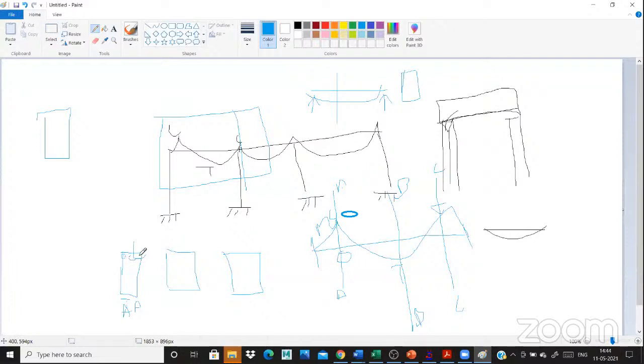So you provide the rebar in the compression zone. I provide 3 rebars for my compression zone. I provide 2 minimum rebars, minimum only, for the tension zone. Why do I provide 2 minimum rebars? Simple: no moment is there. So I refer to IS 456. The formula is there, I will show. Only 2 rebars will be provided. That is the condition. And then go for the BB section.